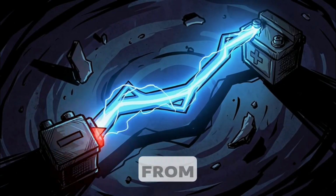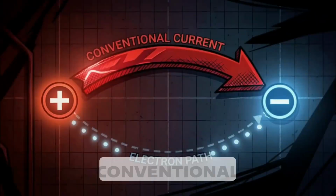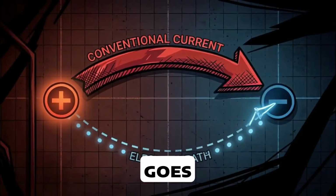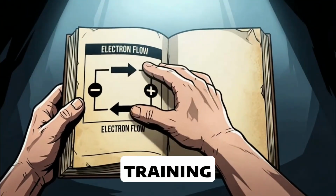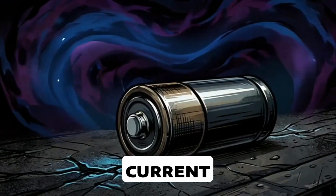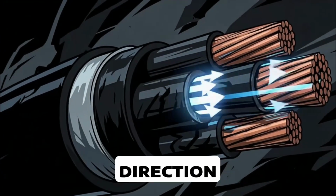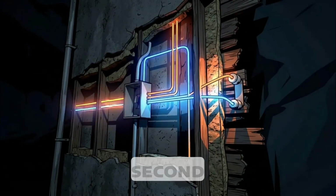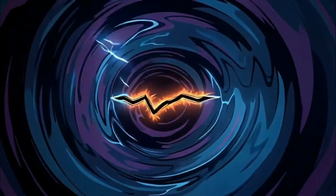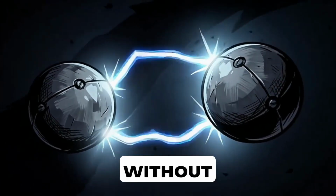Actual electron flow is from negative to positive, but many diagrams and older electrical explanations use conventional current flow, which assumes current goes from positive to negative. You need to know both ideas because both appear in training and wiring discussions. Direct current, DC, means electron flow continues in one direction only, as with batteries. Alternating current, AC, means the direction changes back and forth. In house wiring, the current alternates 120 times per second, which comes from 60 Hz AC, reversing direction every half cycle.